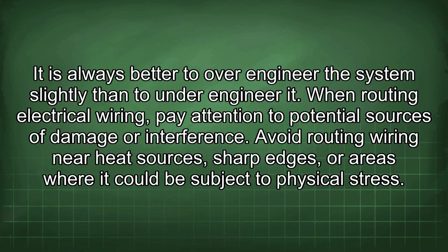When routing electrical wiring, pay attention to potential sources of damage or interference. Avoid routing wiring near heat sources, sharp edges, or areas where it could be subject to physical stress.